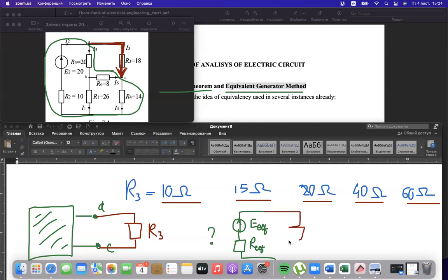But then, after you substitute the resistance, you could find current, power, and voltage with just one formula, dividing your equivalent electromotive force over the two resistances. And it will be quite a bit easier, because instead of calculating a 3 by 3 matrix, a system of equations, 5 times, you could only substitute 5 numbers in one formula and obtain 5 numbers without any system.